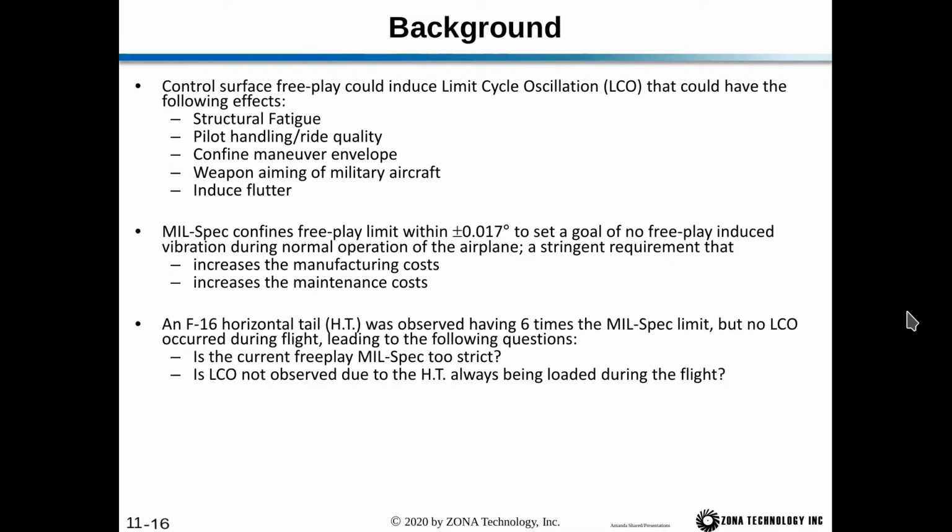So to avoid these issues, the mil-spec confines the Freeplay limit to within plus or minus 0.017 degrees, which sets a goal of no Freeplay-induced vibration during normal operation of the airplane. This plus or minus 0.017 degree allowable Freeplay limit is a stringent requirement that increases manufacturing costs and maintenance costs because this is a very small Freeplay value. It's a very tight tolerance. However, an F-16 horizontal tail was observed having 6 times the mil-spec limit, but no LCO occurred during the flight.